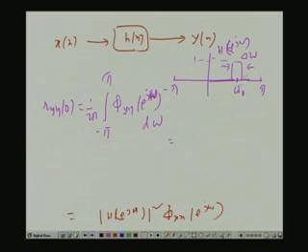So, it is a question of finding the value of input power spectral density at the center point omega naught. Assume that it remains constant or flat over the entire band, because the band is infinitely small. So the overall area becomes nothing but 1 by 2 pi times phi x x e to the power j omega naught times delta omega, and this must be greater than or equal to 0, which means power spectral density is a non-negative function.